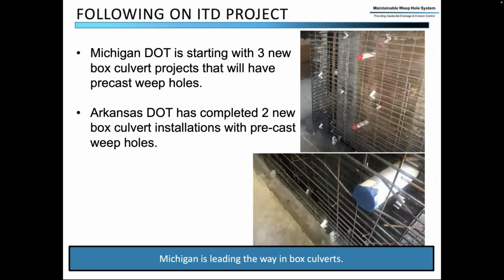And what can you tell us about Dickinson County and what they've done? Well, Dickinson County had 6 roads that were going over creeks. This is an area in the Upper Peninsula that has a whole lot of traffic from logging. And as David had said before, soil can be disturbed with the heavy trucks on the road. And they had been losing soil and dropped down the approach 8 inches from the box culvert.